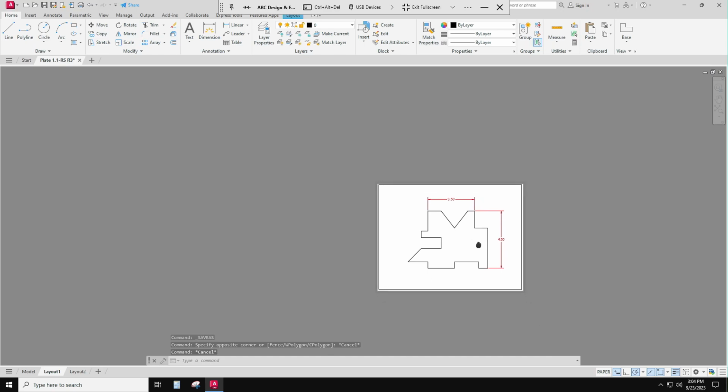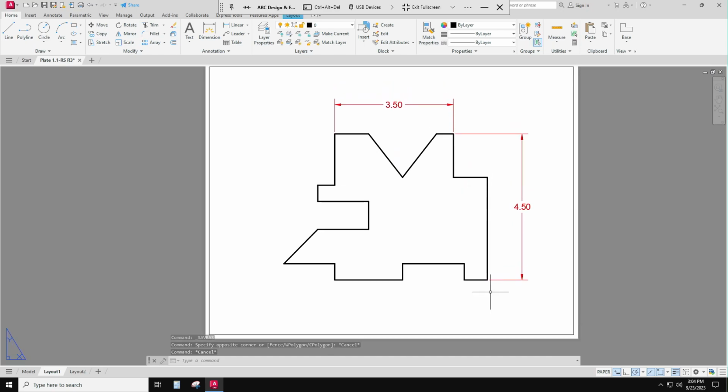So that's gonna be a piece of text. I'm gonna go up to my layer properties, make sure that what I do is going to go on the dim text, and it's something called the DT command. And I want my letters to be 0.18 high on the dim text layer and right justified. That means the right side matches up.